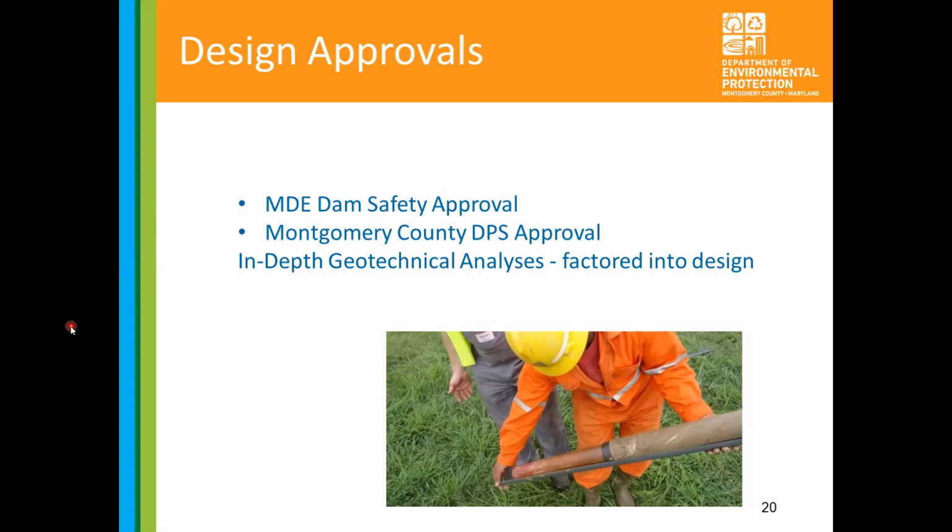And there were quite a bit of geotechnical analyses performed, which I'm sure you were all aware of, seeing the drill rigs on the embankment for those that stopped by while we were drilling. The data from these was used to help with slope stability analyses, which basically model how the embankment is going to perform under these conditions, both existing and proposed.